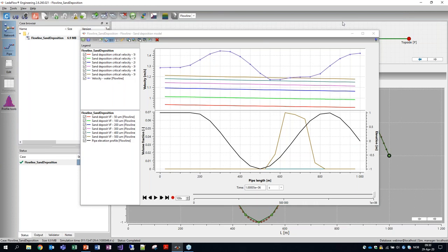The sand deposition model depends mainly on the water flow rates. Does it also work with other liquid hydrocarbons? Any modifications planned? We don't really plan to modify this, because in most situations the sand would be wetted by the water, and it mostly prefers to travel with the water phase, not so much with the oil. So no development is planned at the moment unless we find out we need to do that.